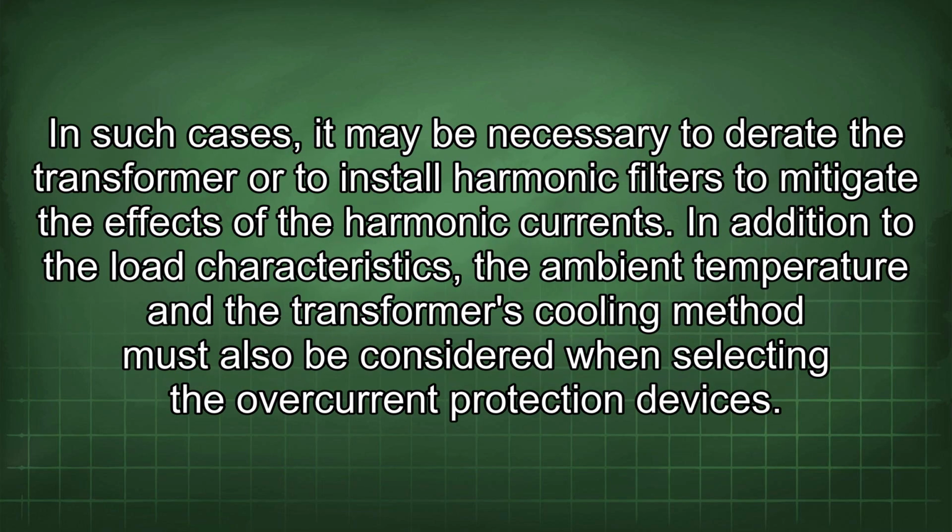In such cases, it may be necessary to derate the transformer or to install harmonic filters to mitigate the effects of the harmonic current. In addition to the load characteristics, the ambient temperature and the transformer's cooling method must also be considered when selecting the overcurrent protection devices.